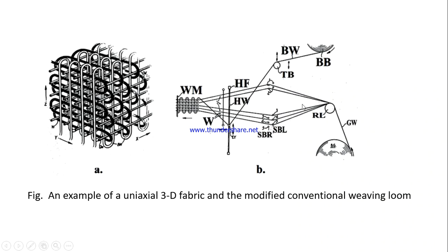You know, in the conventional loom there will be a single warp yarn and a single set of weft yarn. But here many sets will be produced and many wefts will be inserted in each and every set. You can see 1, 2, 3, 4, 5 sets are produced here, and 5 yarns are actually inserted, and after that the binder yarn will wrap over all the inserted weft yarn.